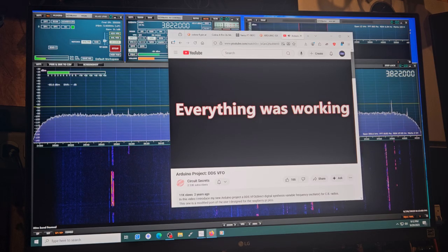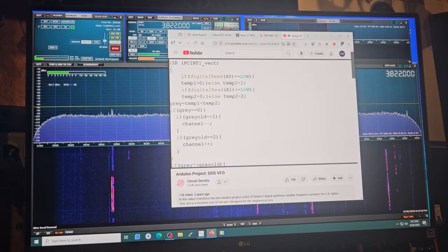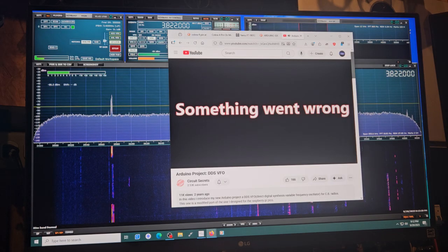The next step was to add the encoder, at first without interrupts, just to see if it would work with the menu and channel selection controls. When I uploaded the sketch to the Arduino, the upload would go fine, but the Pro Mini would not display anything. After trying a lot of things and double-checking the hardware with the diagnostic method I used before, I found the problem.